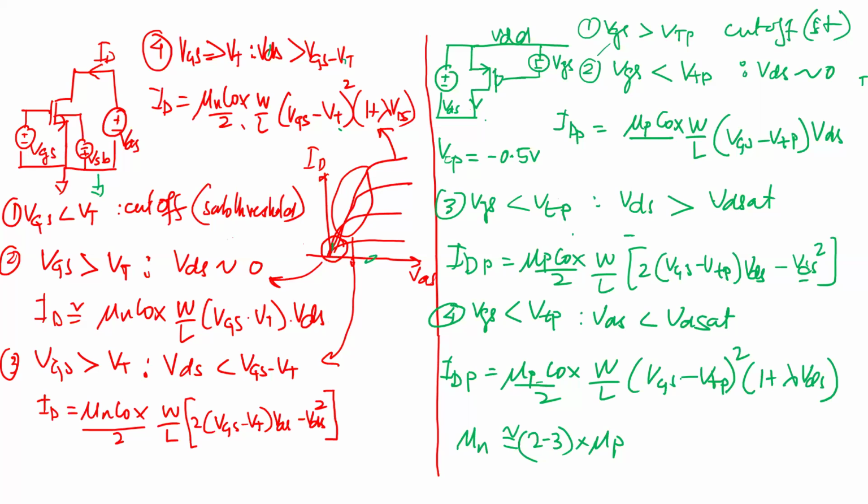Because what happens is you take silicon, and the way the silicon dioxide is made is you heat it to a large temperature, like 1,000 degrees, or maybe 1,500, I forget exactly how much. And then you pass moisture over it. So it starts oxidizing, okay? And then it becomes silicon dioxide. So that's how you grow silicon dioxide. Now, once silicon dioxide is formed, the oxidation happens pretty well. But the first layer which forms with the silicon itself is still very sort of nasty.